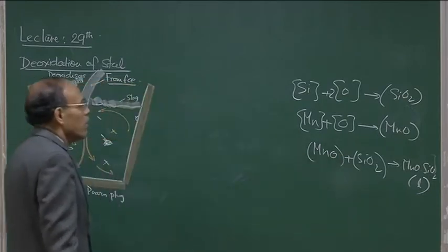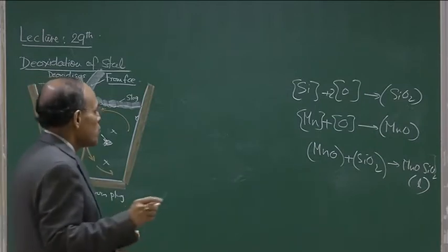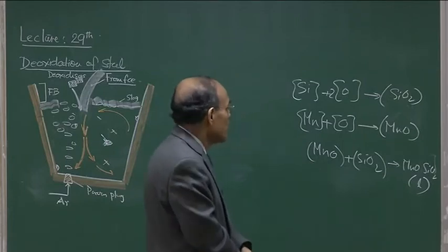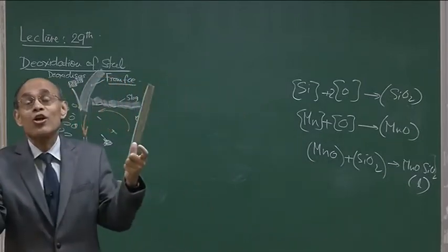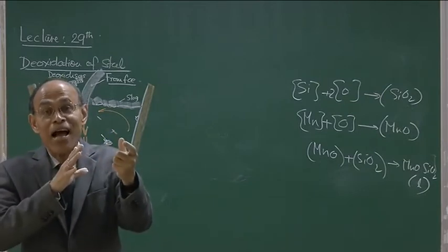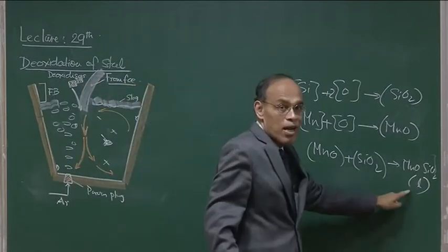In terms of mole ratios, there is roughly a 1:1 mole ratio if they combine. If you use a silicomanganese where you have 70% Si and 30% Mn, for example, then you may not get a liquid deoxidation product itself.